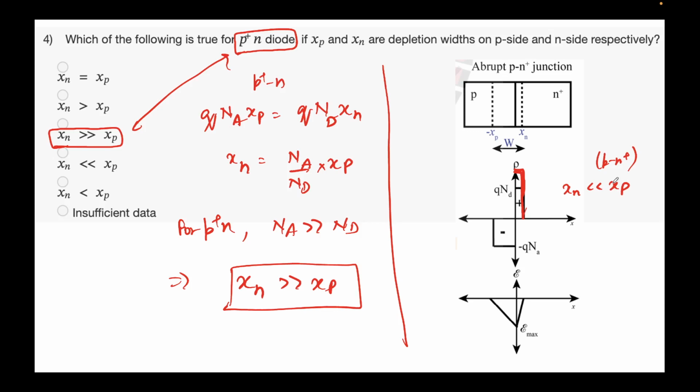For the gallium arsenide problem, we saw that there's a difference of 20 times between the dopings on both sides. And we also saw that the depletion width was 95% in one region. In the last problem, we saw that there was a difference in doping of 4 times, and again the same thing was coming in the depletion widths as the doping. So just keep these things in mind. Okay, that's all. That's the summary, the takeaway I want you to have here.